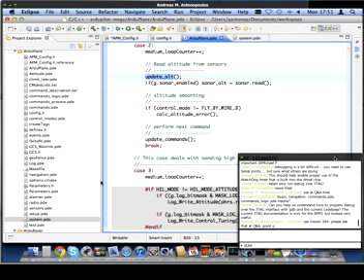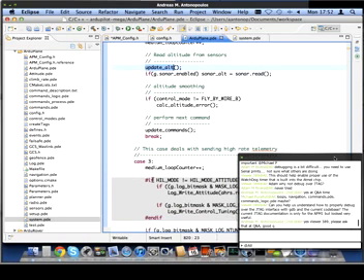So update out does a barometer read, but in between times there will have been 8 samples of pressure and 2 samples of temperature. It does a 4-to-1 split between pressure and temperature in its interrupt read routine, which means we are actually reading and averaging the pressure at 80 hertz rather than 10 hertz, which means we now get quite an accurate and smooth measure of the pressure.